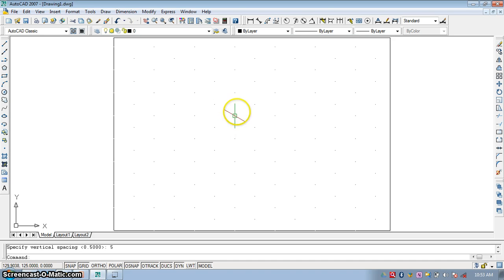If you observe, the grids are now in the isometric view, and in the cursor you will find two lines, one green and the other red. The cursor has three modes, and you can change the mode by using the F5 button or Control E, either one.